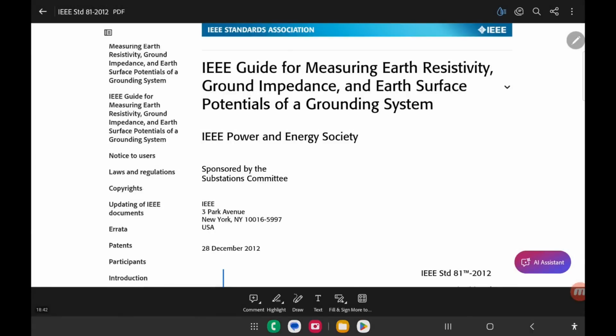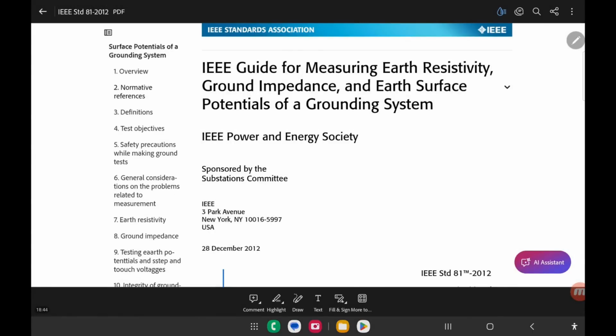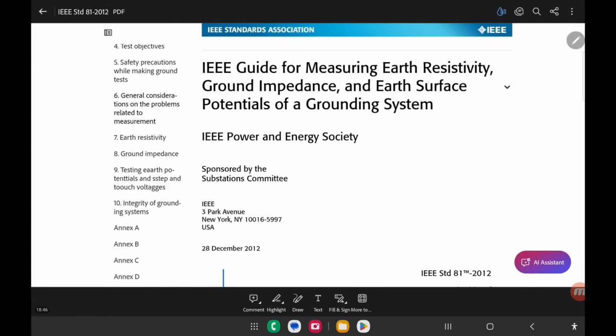And for example, let's look here in point 7, they tell you how to make the measurements, resistivities. But in the measurement of impedance, remember that when we are going to measure resistivity and impedance, we do not use DC voltages because we are not interested in polarizing the bars or test pins.